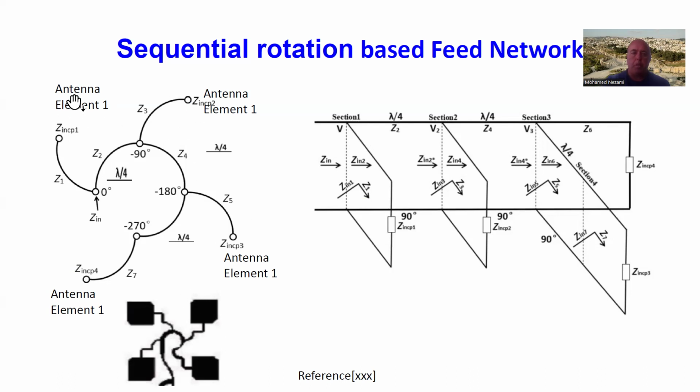So remember this, recognize this. All of the elements are designed so that we have the same impedances on all these lines. So these lines in here all have the same length and the same width, okay? Because they're same impedances. And of course, now it's up to you whether this line here is really the impedance of the antenna, or you can use it as a quarter wave, extend it as a quarter wave transformer to do matching for the antenna patch.